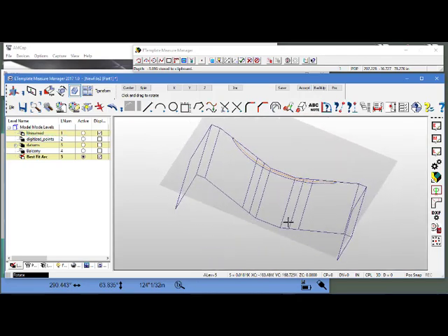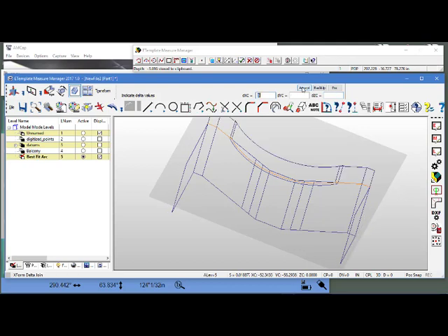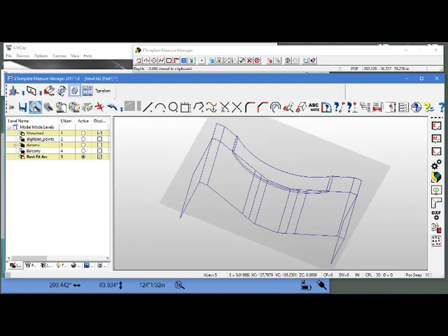Now I could further extrude sections of this to get like a railing. Single. So I want this piece, this top piece, this piece, and this piece. And I'm going to accept that. And I'm going to make one copy. No changes to X and Y again. This time I'm going to say, I don't know how high they should be. I'm going to say 36 inches. Hit accept. And now I've got the second floor railing. Got this tool, bring it into focus. So we have here our digital representation of this room with a second floor balcony and the handrail.